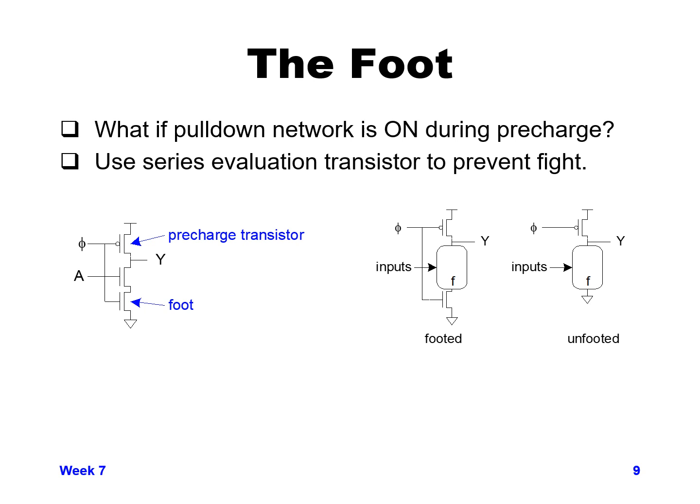If we had more of a generalized function, you can see the schematic in the middle, just to the left of the rightmost schematic there, where we have a logical function with multiple inputs coming into it. That entire function is an NMOS network of some sort, and that full network needs to be in series with this foot NMOS that is connected to our clock, that is also connected to our PMOS pre-charge device. So you can see in the middle there is a footed domino, and typically I'll call that a D1 type domino.